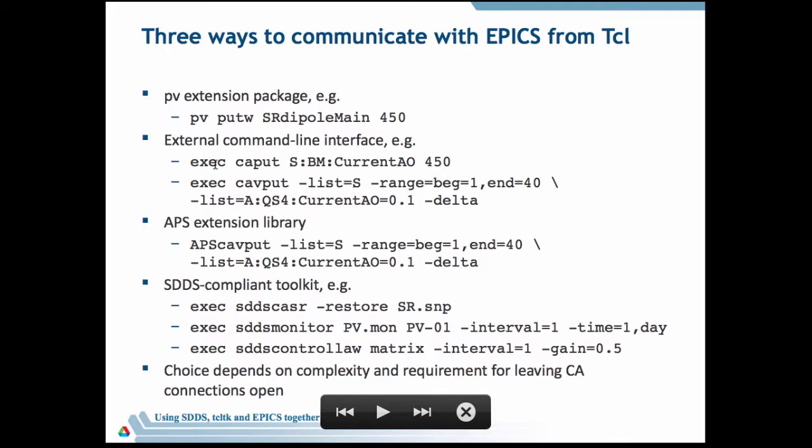Because the IOC has limited resources, you have to close after you open it. So if this is in a loop running very fast, you can overwhelm the network and the IOC if you keep opening and closing the same channel over and over again. This library call only opens the first time, and if there's a loop, it keeps the channel open.